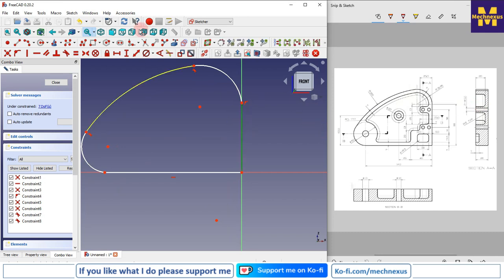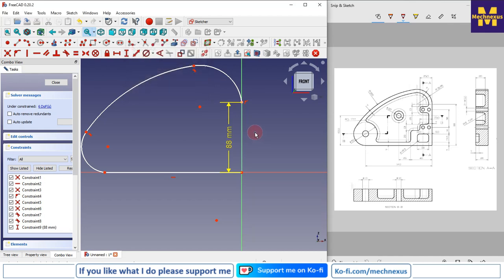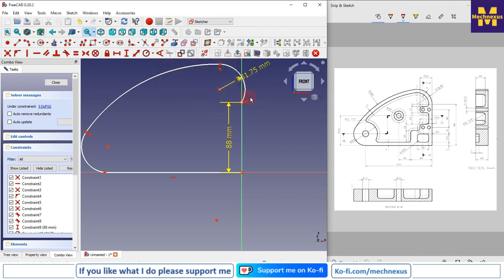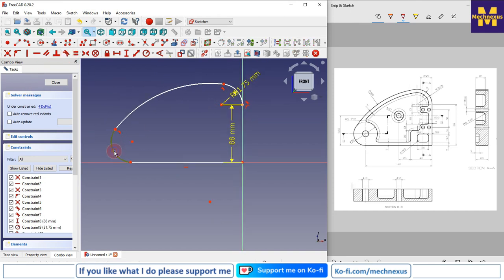So this is 88, and this radius is 31.75, so I will give here 31.75, and then I will make it tangent, and this one is R25,